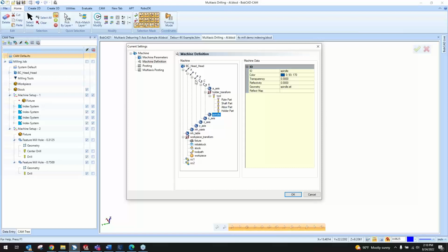You can also go to each rotation axis, like that A axis. You could see I wasn't able to rotate it a full 360 degrees and keep rotating it around and around like the C axis rotation of the head there. That's because I can go here to A axis limits. Its limits are plus or minus 120 degrees. So if there are specific limits that you need to set for your specific machine, you can set them. If it's only plus or minus 90, for example, you can set that here.